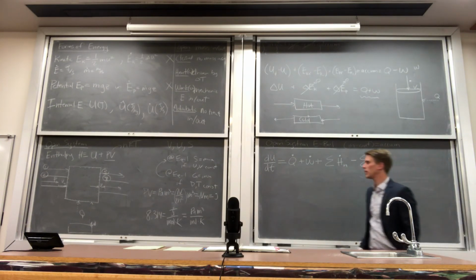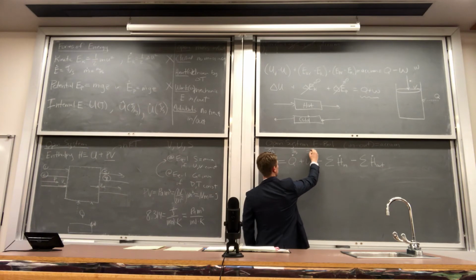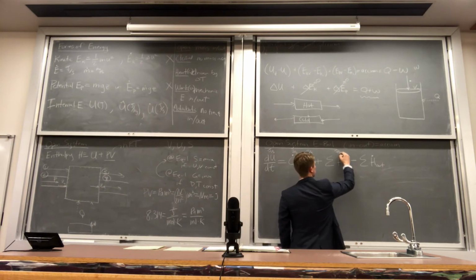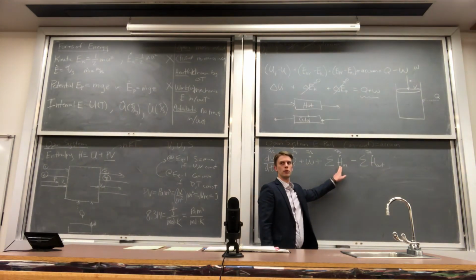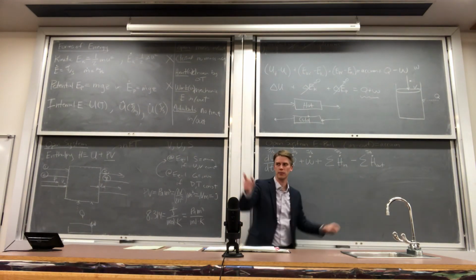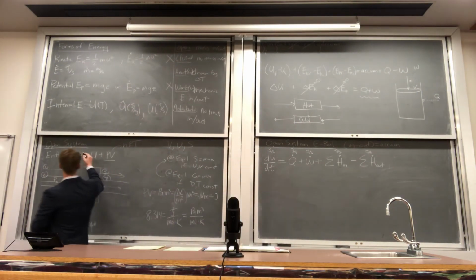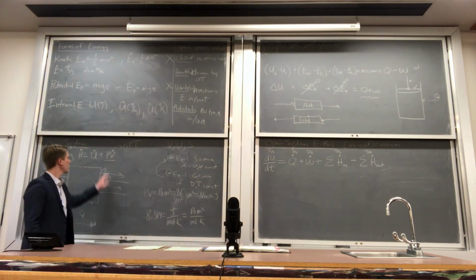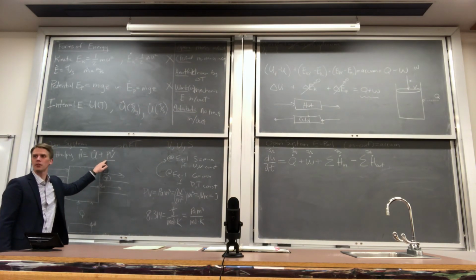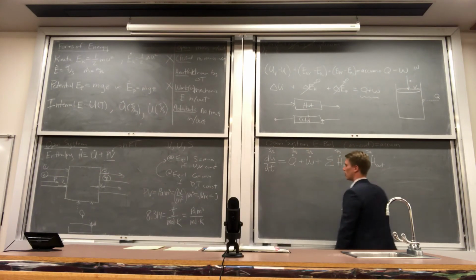Now, this is not generally how we write this expression. Well, let's double check the units. This is joules per second, joules per second, joules per second, joules per second, and joules per second, right? H dot, H has units of joules. The dot over the top means flowing in and out of the system. Yes? So when you write H dot, that would be like U plus PV dot. Correct. Pressure is an intrinsic property, so you can't have it changing as a function of time like that. So this is not how we generally write it, though.